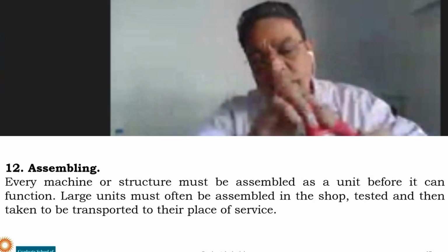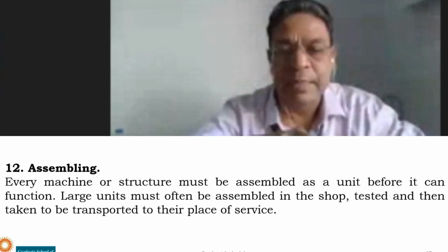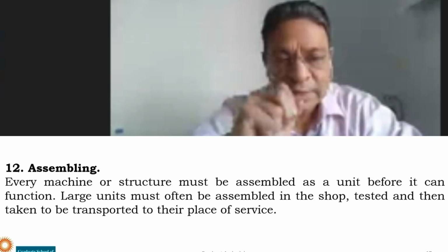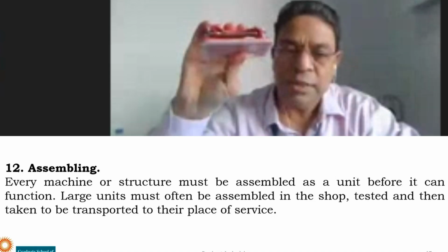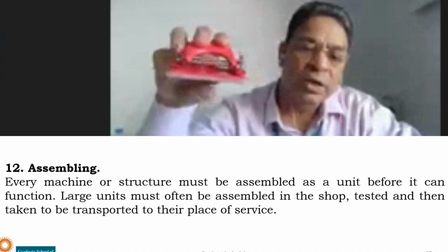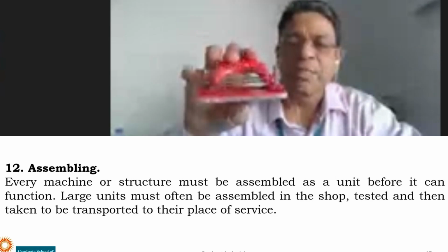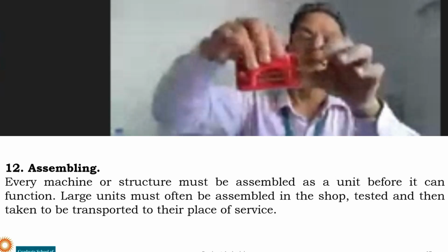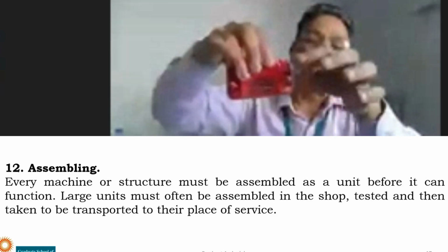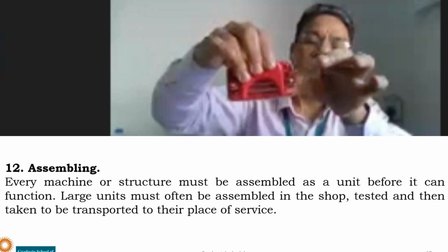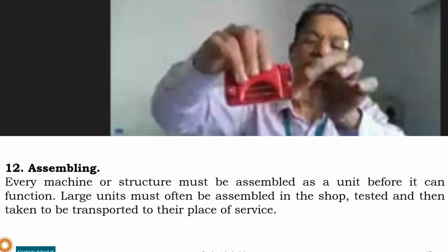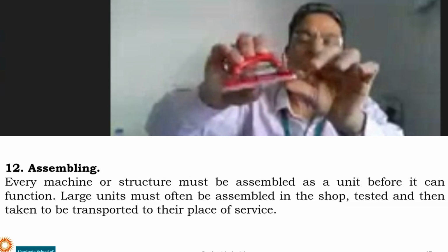Now it can be 100% inspection, or it can be sampling inspection, that we are not discussing here, but the part should be checked. Either the batch should be checked or each and every product should be checked. But then see, if there is no sufficient clearance here, what will happen? This punch will not go inside this and it will not be able to perform the operation.